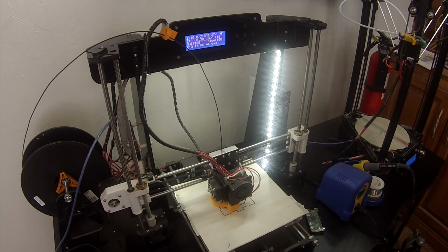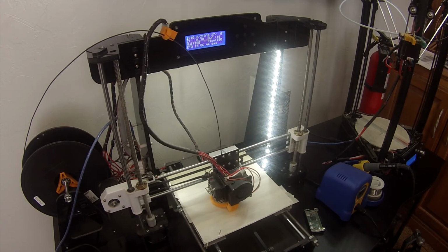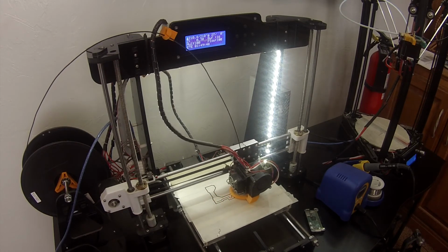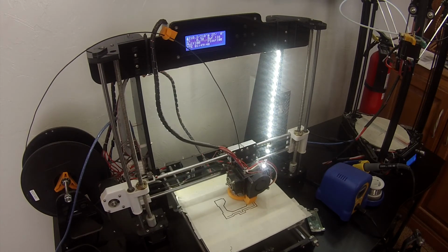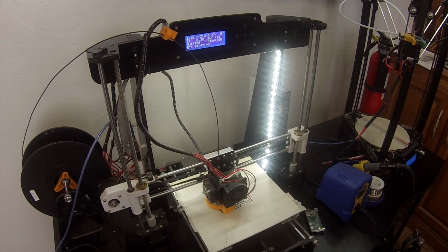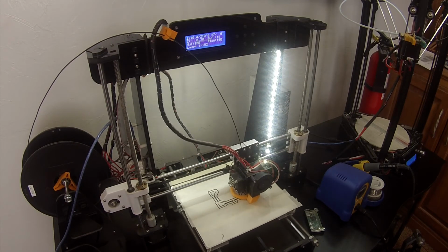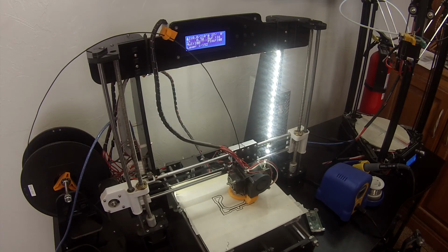So this priming step really does help you lay down a good first layer. And for those of you more seasoned with 3D printing, you might know that the first layer is kind of everything in getting a good 3D print. As long as you have a reliable machine with a reliable code, if the first layer goes down well, it will remain properly adhered, and you should have success with everything else going as planned.